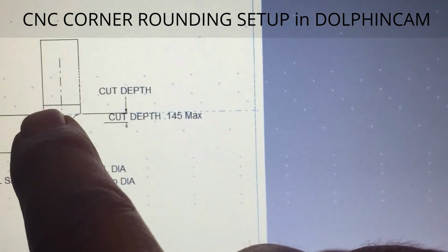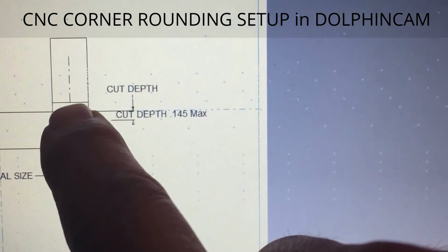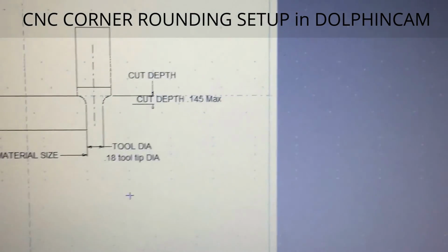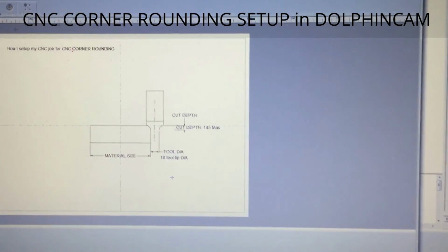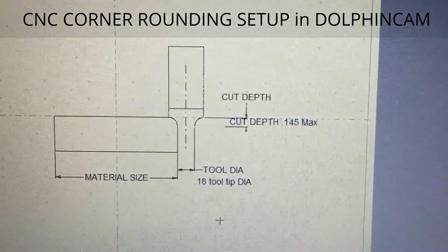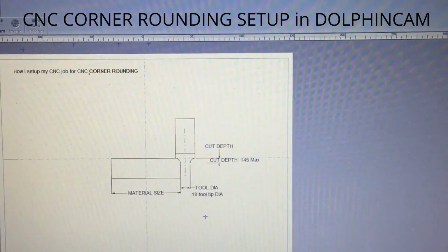Right there, over is the 0.09. So that 0.09 is why I set that as the tool width with an offset left, and that gave me the corner rounding I needed. May not be right. Worked for me, came out fine, and we'll go from there.